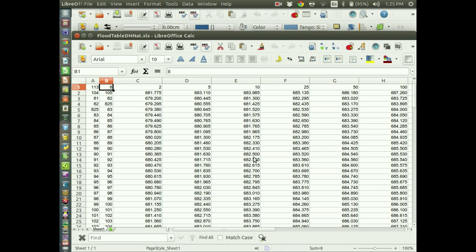So the flood table for Drumheller is a spreadsheet. Basically I had to take this section, say 81, from the cross-section with the flows in section 82, average them, and then populate this spreadsheet. You had to do a number of lookups, and you can do it if you write a program or a script. So then this is actually the flood table.